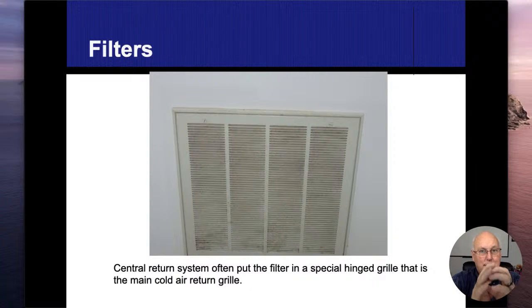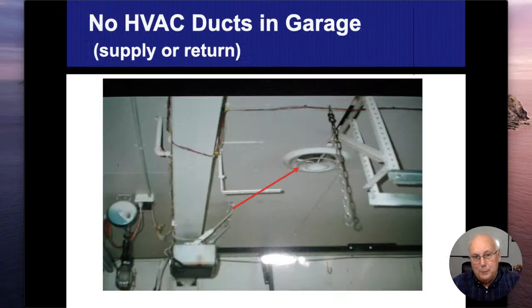Because those metals and that heat exchanger, everything, when it gets hot, it expands. When it gets cold, it shrinks. And they're only designed to work on a certain temperature rise, all right? If I start overheating them or overcooling them, then that shortens their lifespan. We don't want to leave it like that. So making sure we're within that range is kind of a big deal to me.